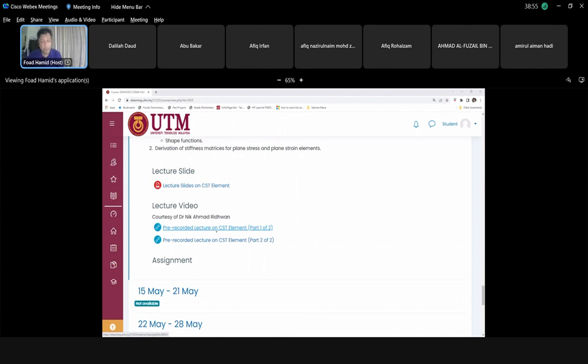After that, we went to the beam element. I showed you last time that the beam element looks like this. We have V and we have V prime. One is what we call vertical or transverse displacement, and the other is rotation. This is V1, this is V1 prime, this is V2, and this is V2 prime. So what we did was we mapped it to Q1, Q2.